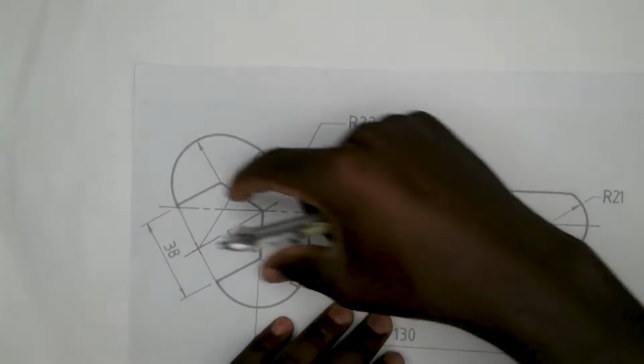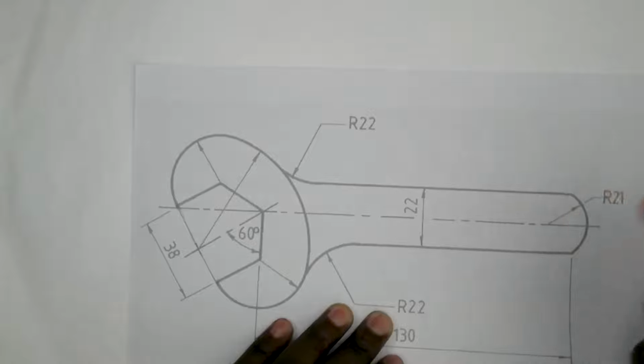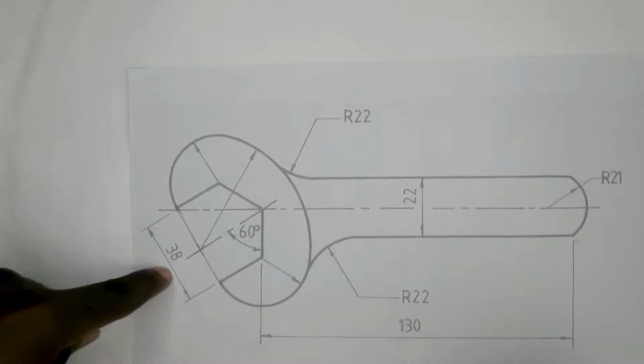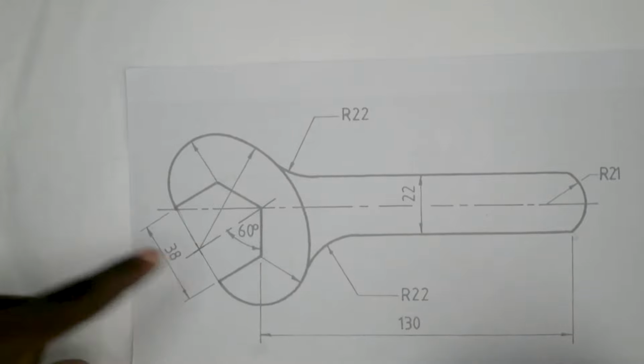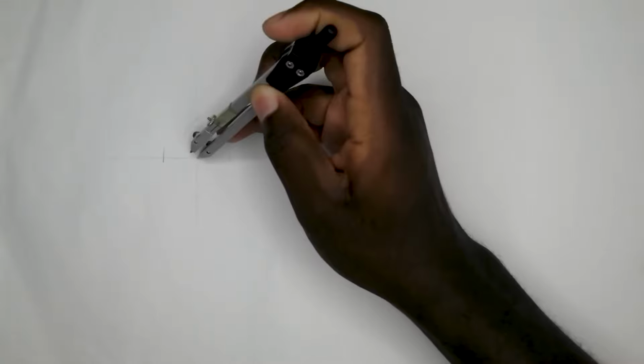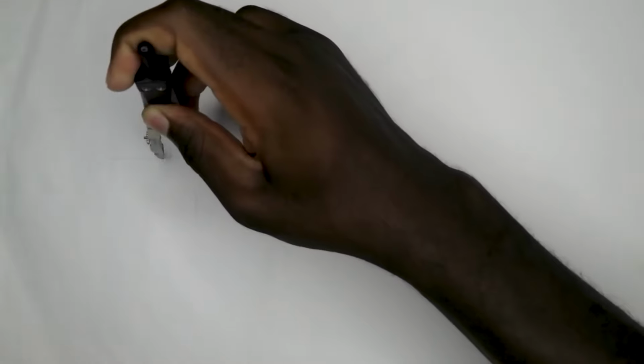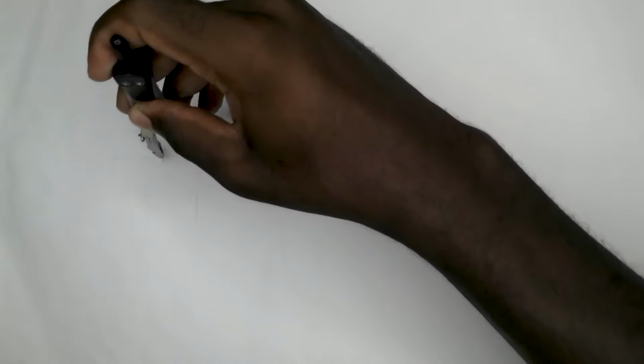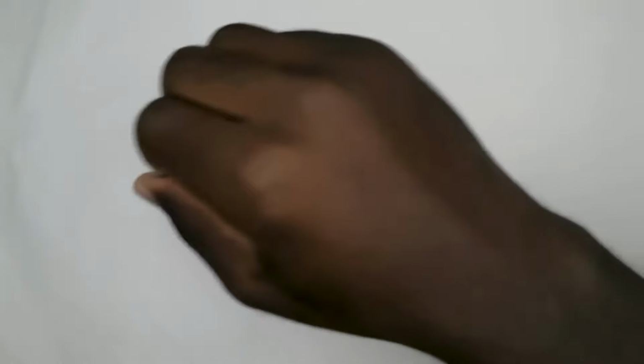But picking your diameter is the more general method in case you have a number like 39. 39 divided by 2 will give you some radius with a decimal point, and you're not really able to mark decimal points so well with a compass. So we'll stand at this point, open to the mark there, which should be the same as opening to the other mark, and then we'll draw a circle.